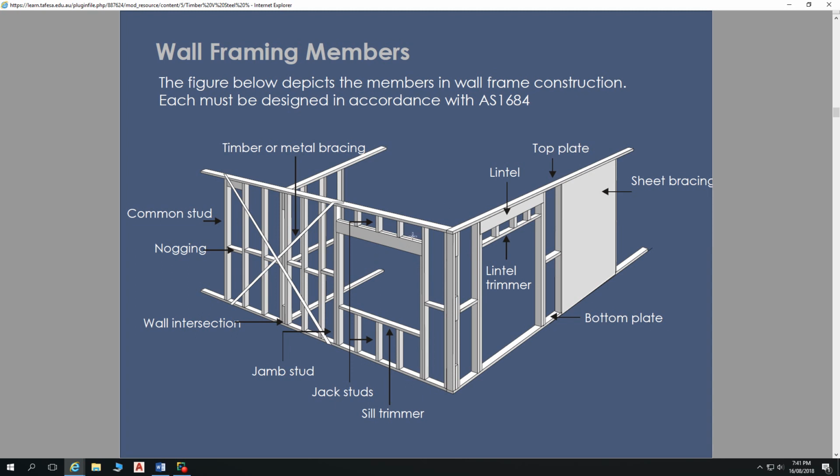But also, you can design it like that, but what chippies do on site may not always reflect in your design and your drawing. And sometimes when you are restricted for space, so here we have a large, very wide opening with very little headroom, that lintel might need to be a very big lintel and very thick. In that instance, we might not have the luxury of continuing our jamb studs all the way to the top plate, and we would have to cut them off because our lintel material is as thick, or almost as thick, as our stud material.